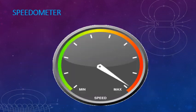The next application is in the speedometer. In a speedometer, a tiny magnet rotates according to the speed of the vehicle and produces the required changing magnetic field. The magnet rotates in an aluminium drum. The eddy current set up increases as the speed of the vehicle increases. Using a calibrated scale, the speed of the vehicle can be obtained.